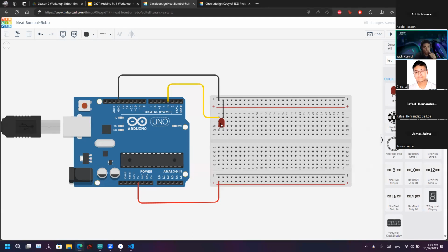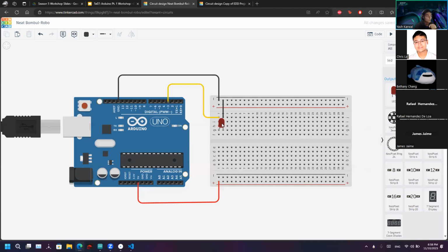Correct. You need a resistor. If you don't use a resistor for this, so again, like Ohm's law here. There's some resistance in the circuit, and there's some internal resistance of the actual LED itself, but it's very small. So what will happen is this will draw a lot of current that will end up causing an explosion. And you can actually see that if you program this later. So we'll program this right now without the resistor, and we'll see what happens to the actual LED itself.